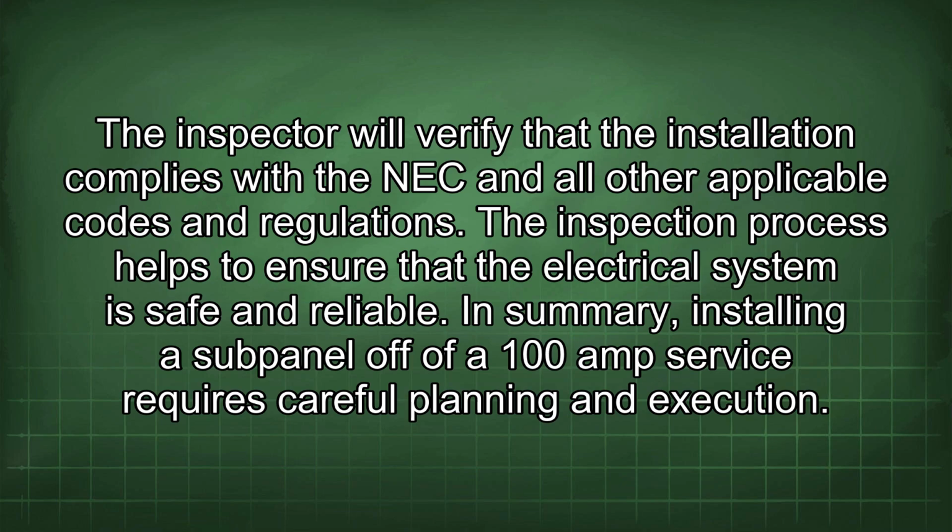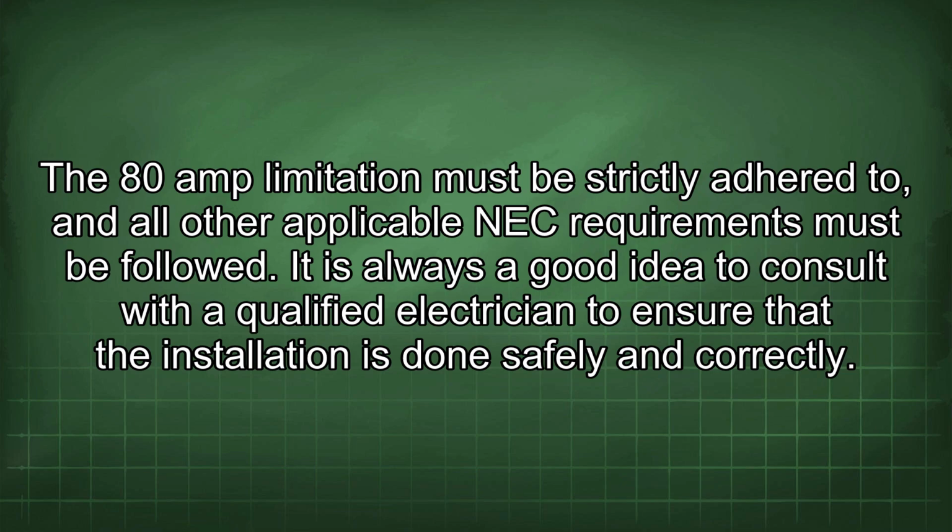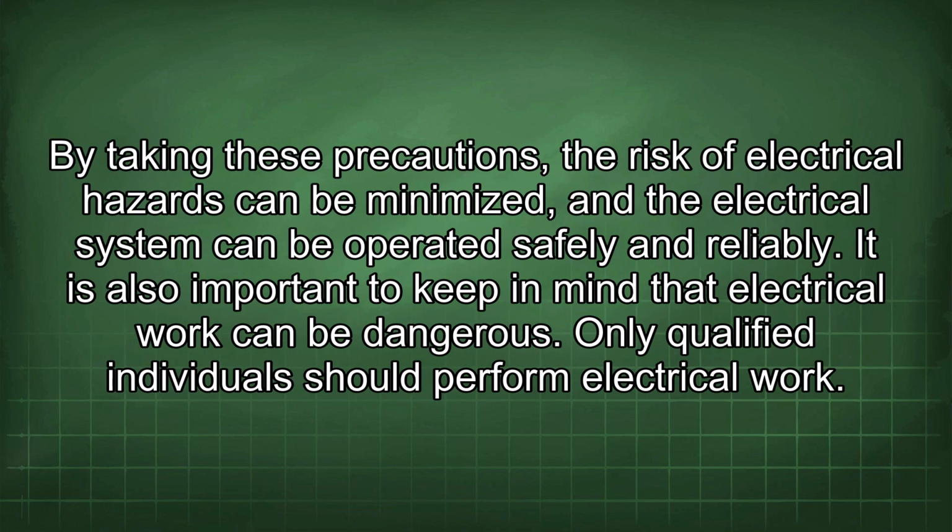In summary, installing a subpanel off of a 100 amp service requires careful planning and execution. The 80 amp limitation must be strictly adhered to, and all other applicable NEC requirements must be followed. It is always a good idea to consult with a qualified electrician to ensure that the installation is done safely and correctly.